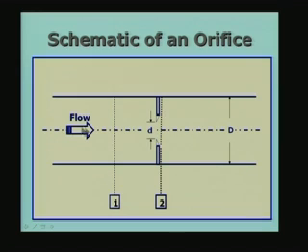Okay. So, the flow coming here, because it has to pass through the small hole, is going to accelerate as it comes towards the hole, and how does it accelerate? The pressure energy is converted to kinetic energy, because kinetic energy is increasing, and it comes from the pressure. The potential energy is converted to kinetic energy, therefore the velocity is larger here as compared to here, and that is what happens.